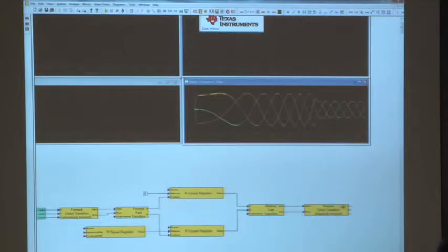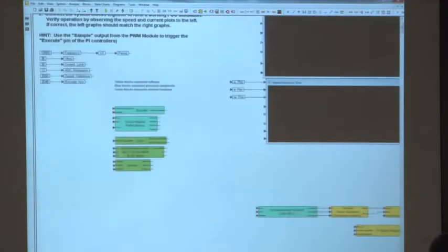Okay, so now I have VU, VV, and VW. What do I want to do with those? Voltage A, B, and C. I said put them on the motor, right? Well, okay, but those only exist as 0 to 1 signals so far. I want to run them first through a PWM module. So I'm going to take those values and drop them into my PWM module.